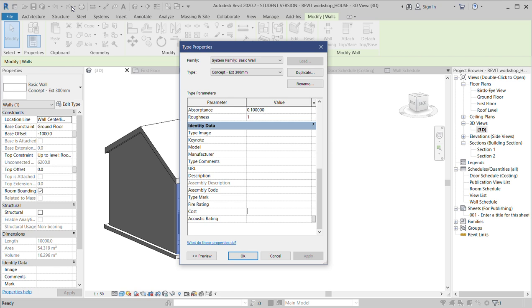So if you know what that wall costs as a complete wall type per meter squared to construct, you can add this cost in. So for example, that type of wall build might cost around £265, based on figures I found in some other projects. So that wall constructed with those layers attached to it as a built construction cost is £265 per meter squared.